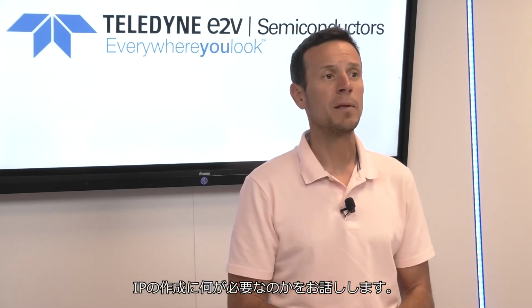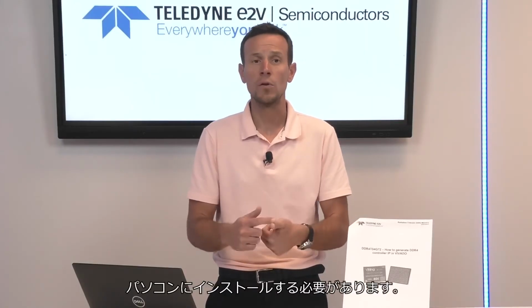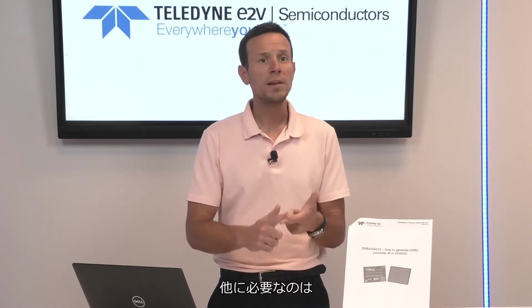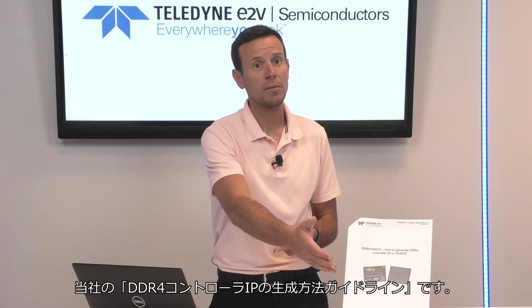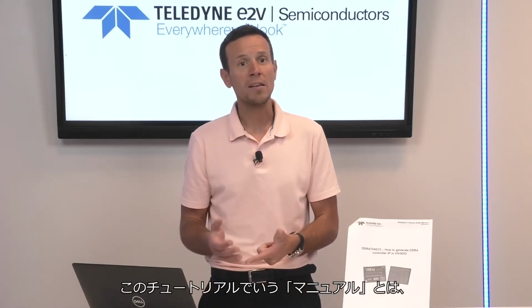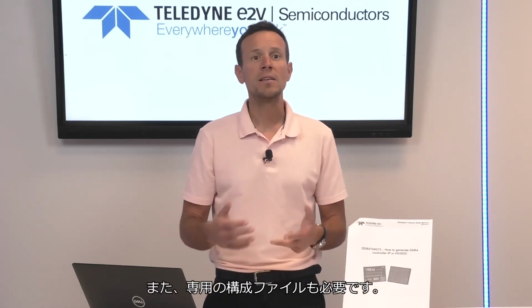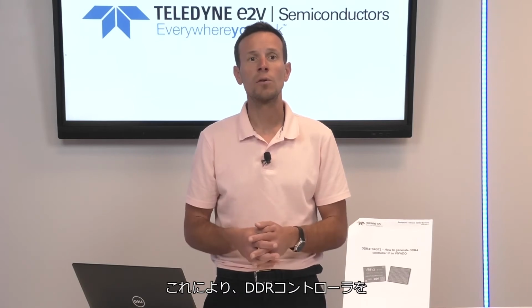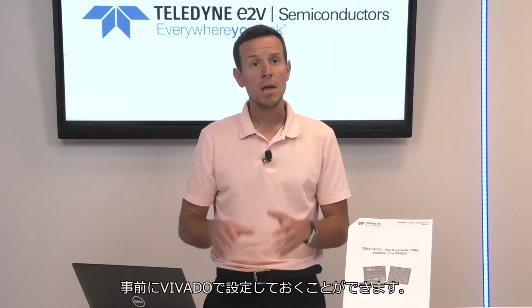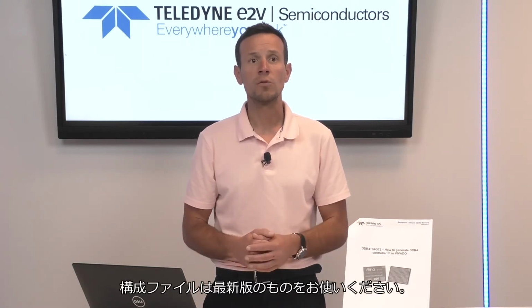First, let's talk about what you will need to generate the IP. You will need Xilinx Vivado development tool installed on your computer. You will need our How to Generate a DDR4 Controller IP in Vivado guideline, which I will refer to as the manual throughout this tutorial, and you will need our dedicated configuration files that allow to pre-configure the DDR4 controller in Vivado. Before starting, always make sure to get the latest version of the configuration file.